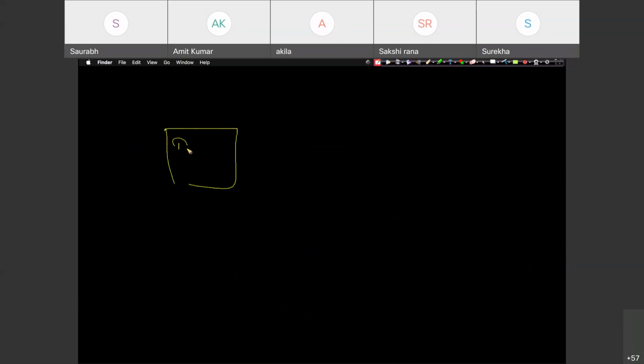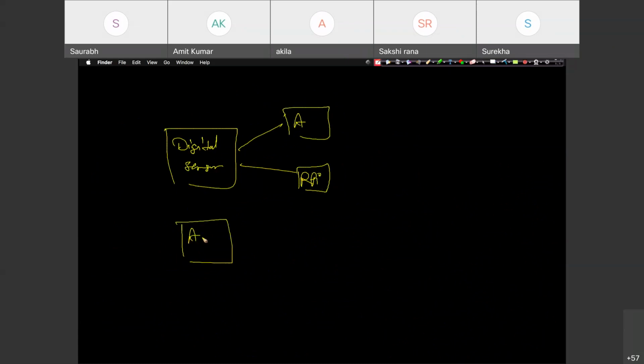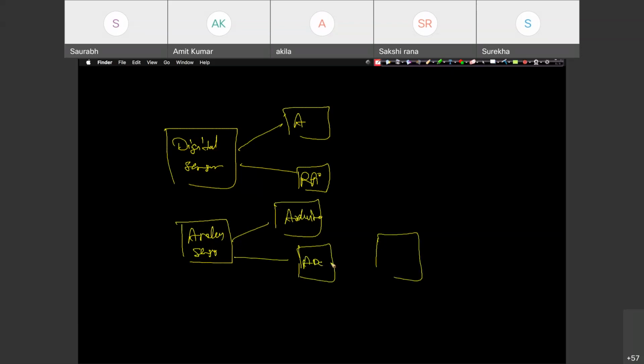If your sensor is a digital sensor, then you can work with both Arduino or Raspberry Pi. If your sensor is an analog sensor, right? So you can work with an Arduino directly. But before working with Raspberry Pi, again you have to work with an ADC and then the RPi, then Raspberry Pi. Okay, you should have an ADC, right? If your ADC is just a 1-bit ADC, then you can work directly with a comparator here. Your data will be converted into 1 bit, either high or low.